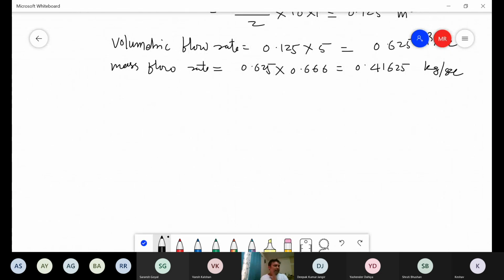Now let us make a complete balance here. So the complete balance in this case is what? m Cp dT, isn't it? So m Cp dT is m Cp (T1 minus T2), isn't it? So this is nothing but the heat lost by the flue gas, and that should be the same as h into area. Let me write it as A_H.